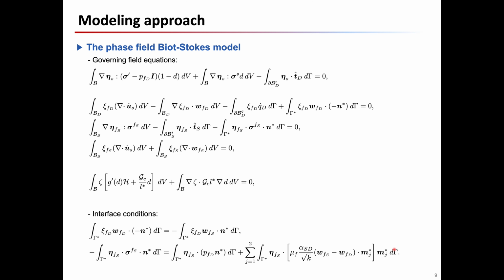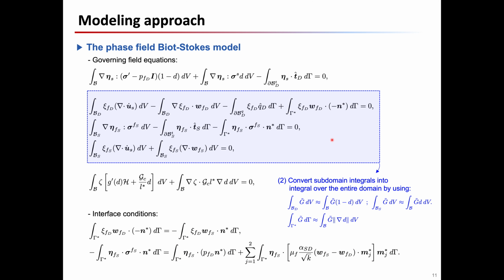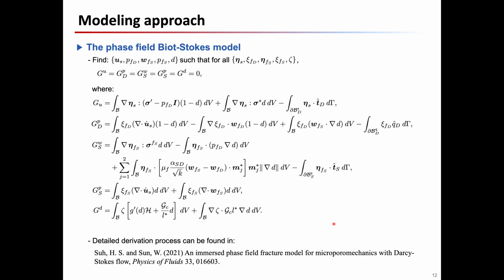By using the standard weighted residual procedure, the weak form of the governing field equations and the interface conditions can be expressed like this. From this weak form, we derive the immersed phase field Biot-Stokes model. We first substitute the interface conditions into the governing field equations like this, and then convert the subdomain integrals into the integral over the entire domain by using the smooth interface approximation.